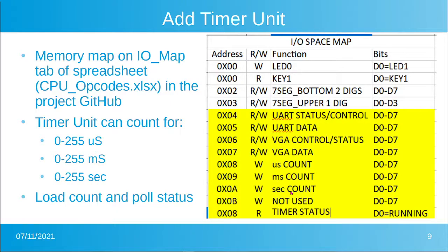Well, you might ask, what if you want to count between 256 microseconds and 1 millisecond? Well, you can just call it a couple of times. These are reasonable numbers for most of the kind of things you'd want to do. Usually you're in the orders of microseconds, milliseconds, seconds. 255 seconds, that would just get to be a lot, but more perfectly reasonable, and that limitation is there because we only have an 8-bit port to write. Now it could be written in 2 writes with a couple extra bits to scale it up, but there's really not a lot of point for it in real applications.